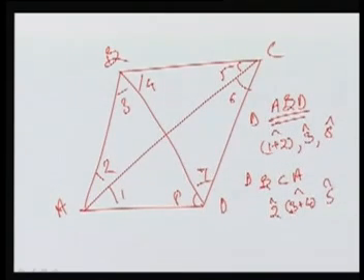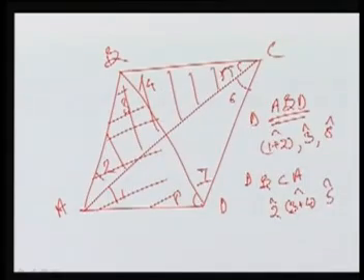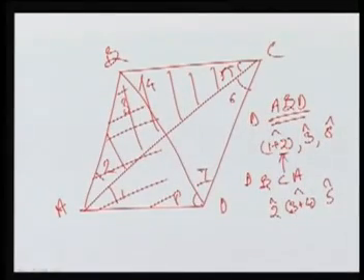So what we are seeing here is, if I adjust this Brice quadrilateral in parts, I am adjusting only this triangle first. I have the adjusted values of the observations inside. Then I can also adjust this particular triangle. Now the angle number 2, for example, has one value here and one value here. So angle number 2 is being adjusted in 2 different ways. So it will have 2 different values, which is not possible. So what I mean to say is, we cannot adjust this kind of problem in parts. Rather, we have to take all the observations together. We have to form one system. In that system, all the observations should participate. Whatever the conditions are, they should be satisfied. It's not that we are adjusting them in parts.